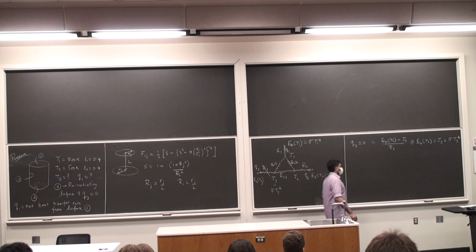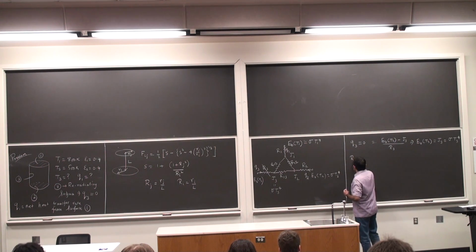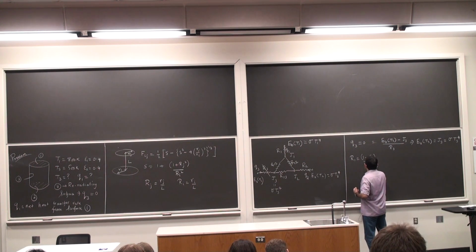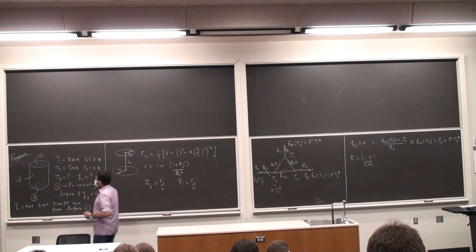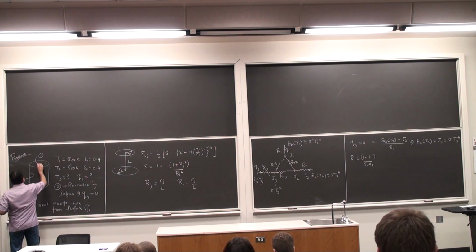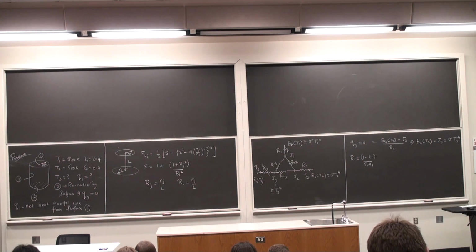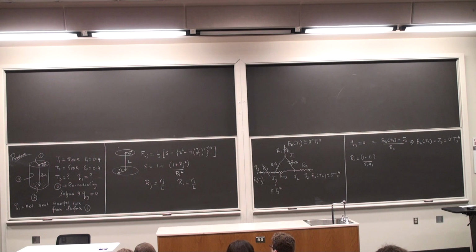Alright, so then let's start calculating R1, R2 and R3. R3 is not needed, so just R1, which is (1 minus epsilon 1) over epsilon 1 A1, and let's say that the radius here, I did not give the geometry, but the radius is 1 meter, and let's say that the height is 2 meters, which we will need for the view factor.